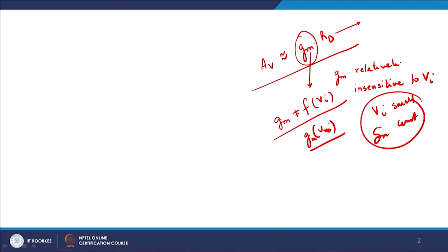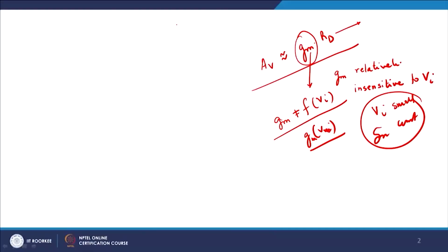We have also seen in the previous discussions that the input impedance of a MOS device is always infinity. So, Rin is typically infinitely large because you are feeding your signal to the gate side, and since the gate side has an oxide layer built into it, you will not have any current, and therefore your resistance, which is voltage by current, with current approximately equal to 0, gives R equals infinity, and that is what the typical input resistance of an amplifier is all about.